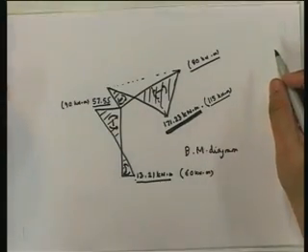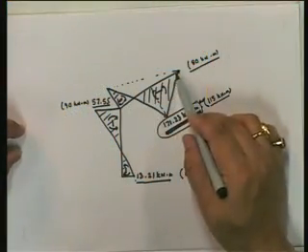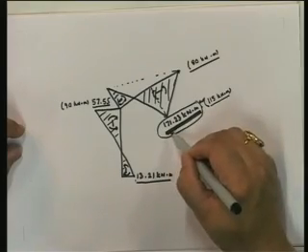In other words, now the member BC, up till now we were seeing, make it flexible, it's going to get much, much better as long as you do not have a serviceability limit. In other words, the rotation and displacement can be anything that it wishes to be. Then we thought that introducing flexibility was being wonderful because it was reducing all kinds of bending moments in the structure. But you have a problem. This particular one is more than 1.5 times, and this member BC has to be designed for this.